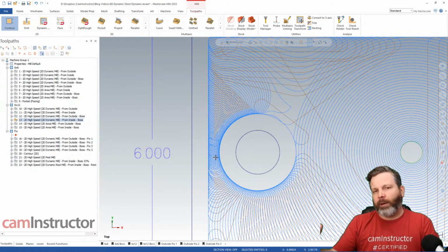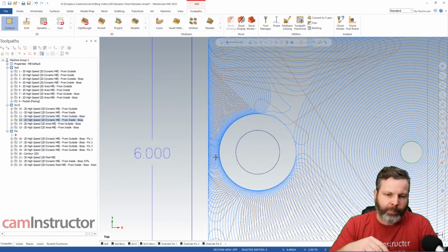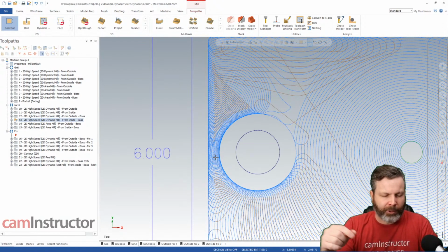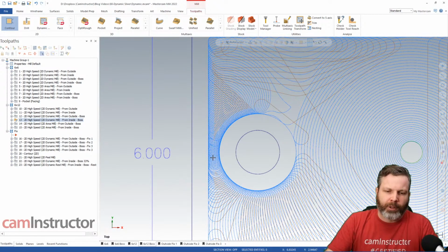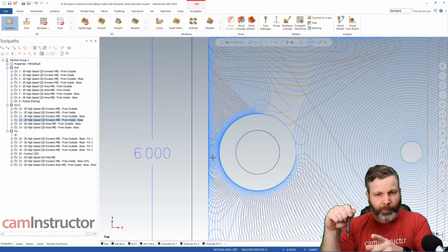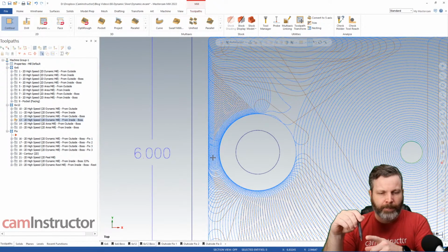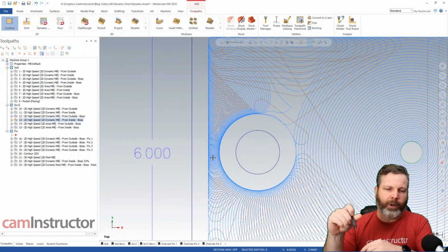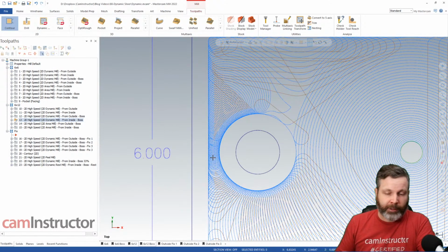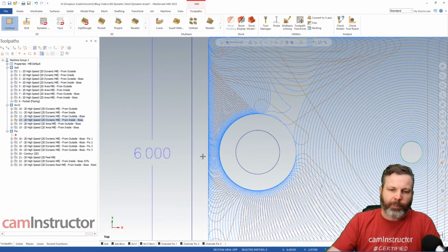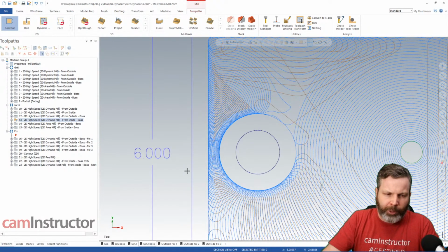But if we take that down to the other extreme and we're talking a 1/8 inch end mill, and we're getting into a very, very small scenario where maybe 10 inches per minute was pushing that tool to the limit, and we're getting into very tiny arcs, where we're exceeding the recommended chip load by 10 times, yeah, you could easily break that 1/8 inch end mill quite easily. So how do we address that? All right, let's get into that.